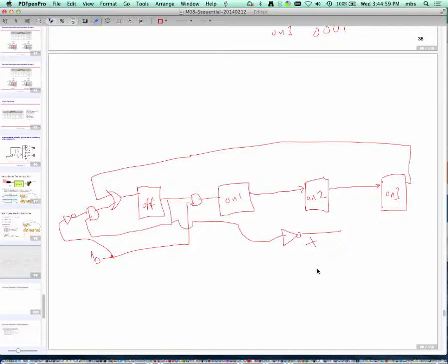Okay. So the first thing you should do is not worry about optimization. Just follow a strategy which is guaranteed to work so that you get at least a design. Then you think about optimization. So again, faced with a problem description, inputs and outputs tend to be obvious usually. What the states are and how you move among the states is where your design comes in. It usually requires a lot of careful parsing of the problem.